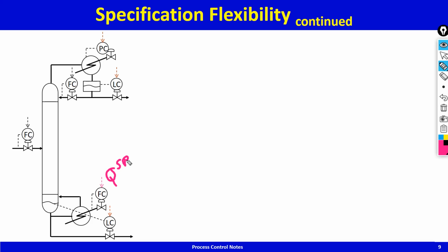And then what we are doing is, we are keeping as before reflux in ratio with the feed, and there is this tray temperature controller which is manipulating the feed rate in order to hold the tray temperature.